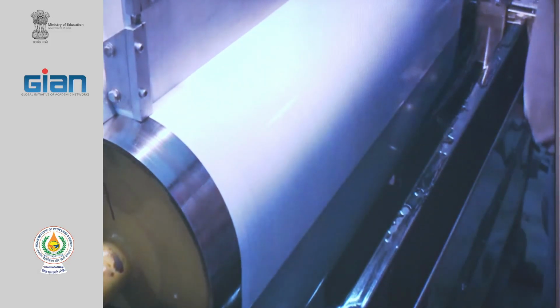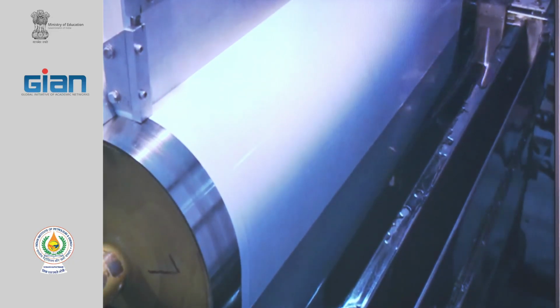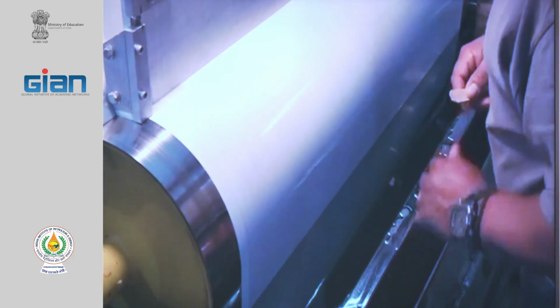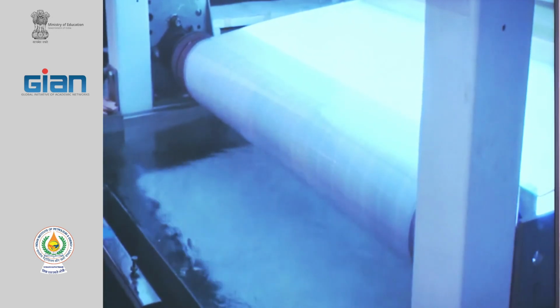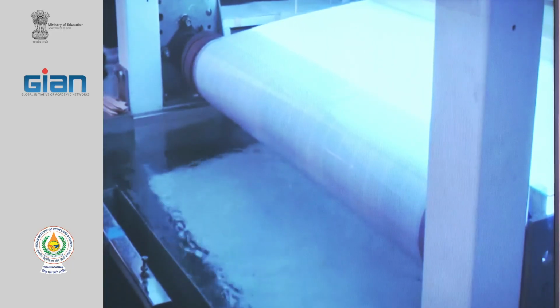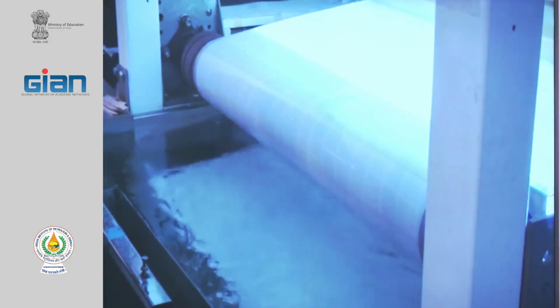200 or 150 micrometers of the polymer solution on the surface of the fabric, and directly goes to the non-solvent. And when it goes to the non-solvent, the liquid polymer solution changes to a solid one. And we say that phase inversion or phase separation occurred.